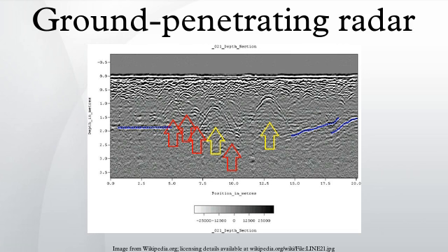The concept of radar is familiar to most people. With ground-penetrating radar, the radar signal, an electromagnetic pulse, is directed into the ground. Subsurface objects and stratigraphy will cause reflections that are picked up by a receiver. The travel time of the reflected signal indicates the depth. Data may be plotted as profiles, as plan view maps isolating specific depths, or as three-dimensional models.